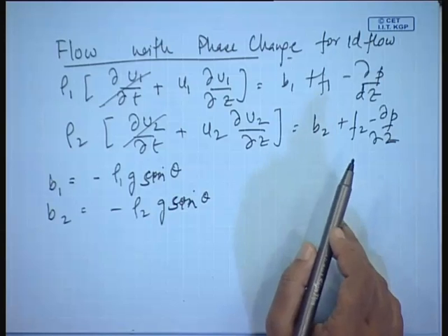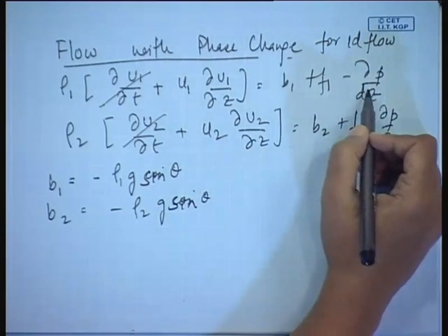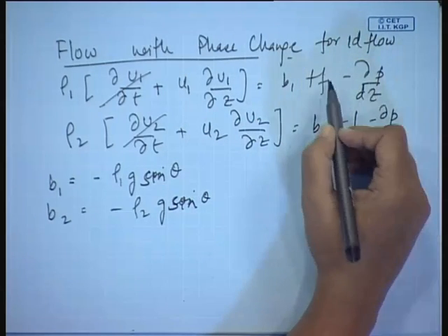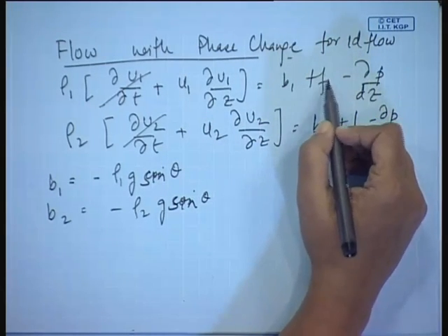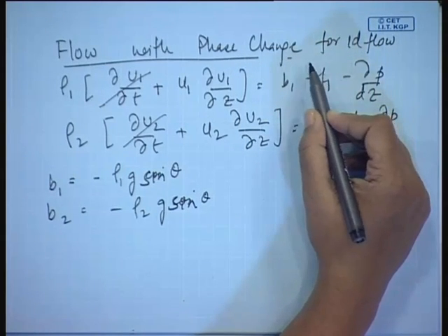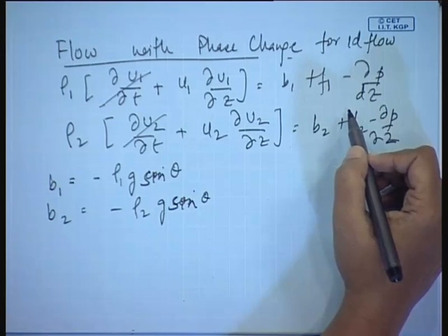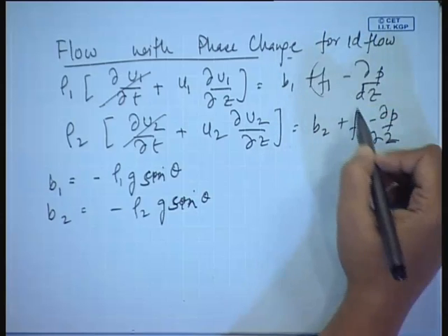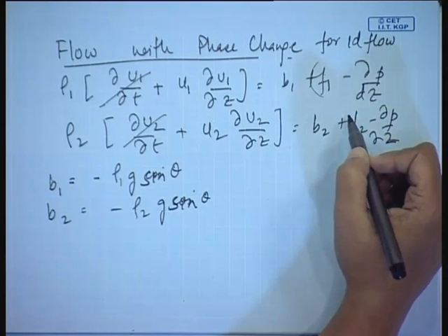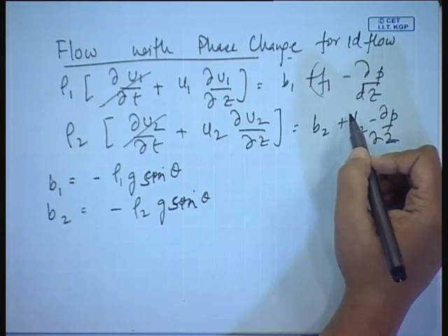But the important part here is that, in order to keep the account straight, whatever extra force is not included in B1 or in the pressure gradient is included in F1 and F2. Therefore, to account for different flow situations, whether it is a drift flux or a separated flow, F1 and F2 are going to be different. Even in separated flow, for annular flow you will have one type of F1 and F2, and if there is a fluidized bed, you have a different type of F1, F2. Is it clear to all of you?